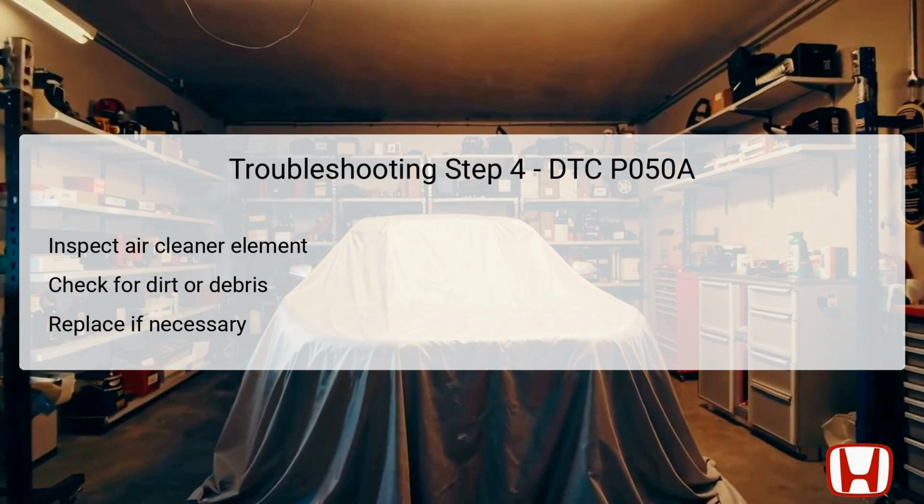If the air cleaner element appears dirty, then replacing it with a new one will enhance the operation of the idle air control system.